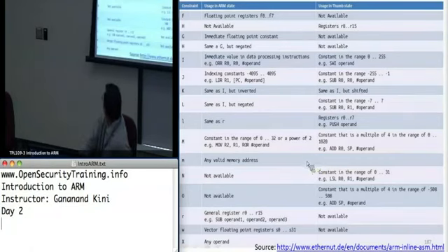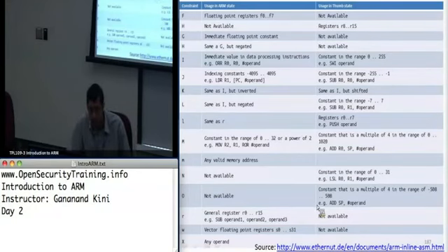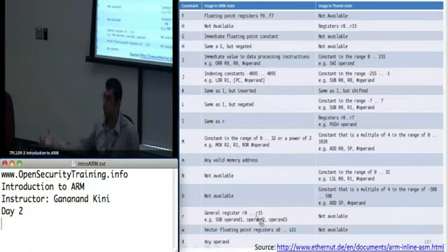And similarly, these are all the available constraints for use in inline assembly. So generally, though, you'll be using R. I've used this, for example, to read the CPSR value after doing a subtraction to check the negative flag. And if I want to check if the negative flag is set after doing a subtraction, for whatever reason in assembly, you can do this kind of operation, but instead of using move, you use MSR or MRS. Actually, you'd use MRS to read the CPSR value into the register.